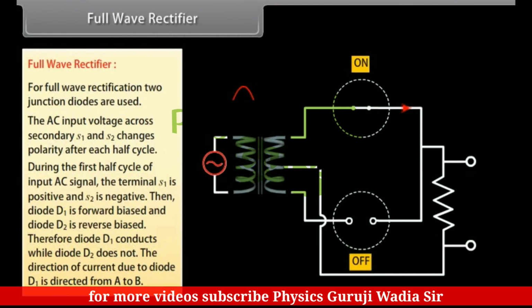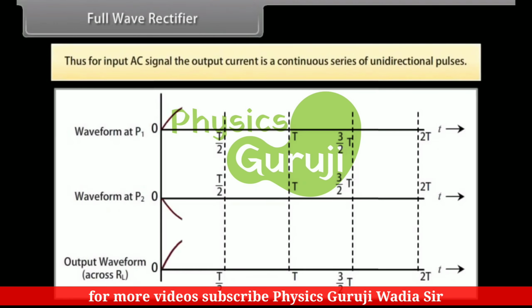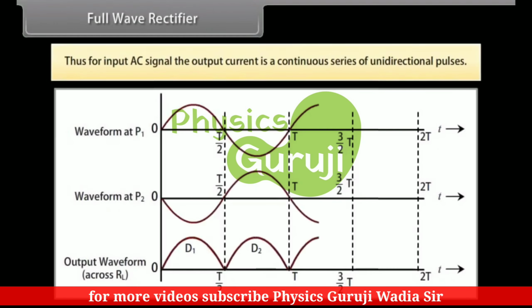The direction of current due to diode D1 is directed from A to B. In the next half cycle, the terminal S1 is negative and S2 is positive. The diode D1 is reverse biased and diode D2 is forward biased. Therefore, diode D2 conducts while D1 does not. The direction of current due to diode D2 is from A to B. Thus, for input AC signal, the output current is a continuous series of unidirectional pulses.